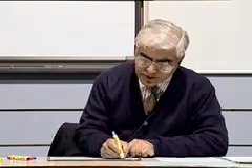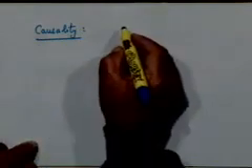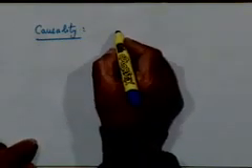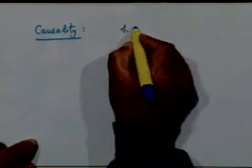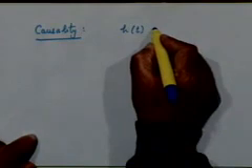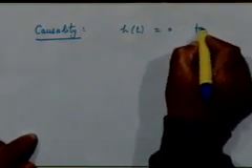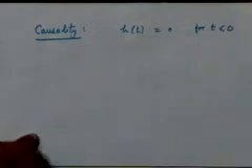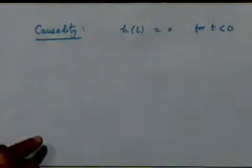Finally, we just note two other important attributes of an LTI system. One relates to causality. We say that a system is causal if the system impulse response h(t) is equal to 0 for t less than 0. This is of course not the definition of causality, but it is a test for causality.